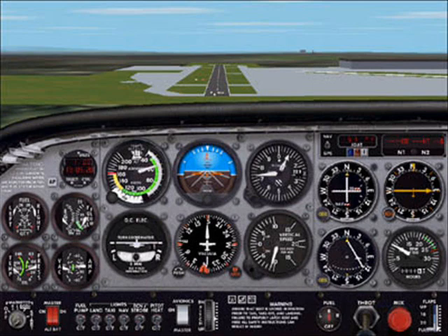The descent rate will also be increased, and the airplane will fly at slightly less of a nose-up pitch as a result of flap application. This is, with flap application, the nose gear isn't as far above the main gear, an additional resource for the flare, as shown in this picture. One of the first things you're sure to notice when using flaps is that the rate of descent is higher. That's why the flare needs to happen a little faster when using flaps.